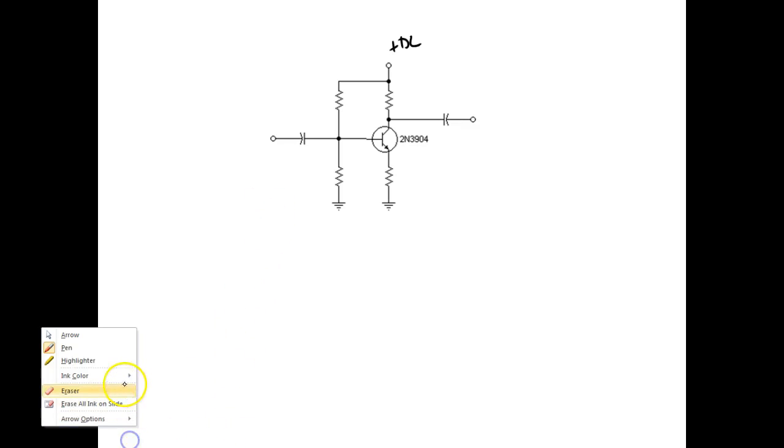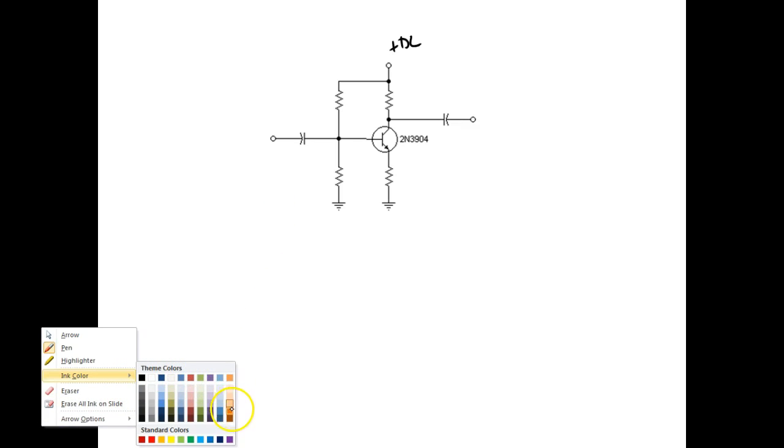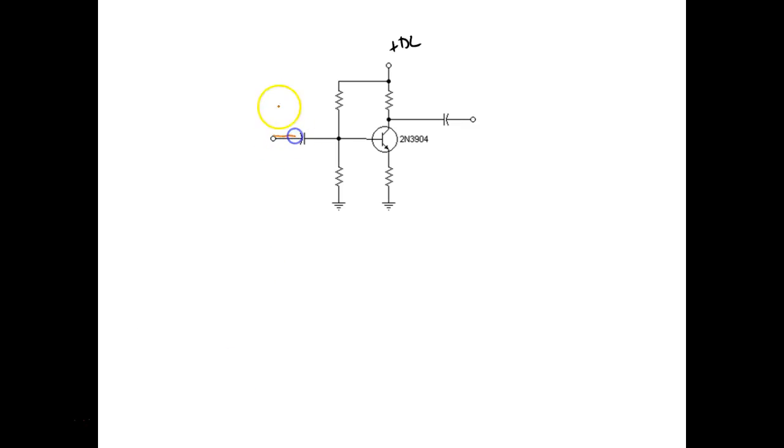So here comes my signal from the input. So I can come over here and have AC. This over here is DC. And I can couple my AC through this capacitor, because what's the general rule of thumb? It does what? Blocks what? DC, and passes what? AC. Now we're going to use a pretty good sized capacitor there, either 100 microfarad or 10 microfarad. We're not going to use any picofarads because it will have a lot of opposition to my AC.